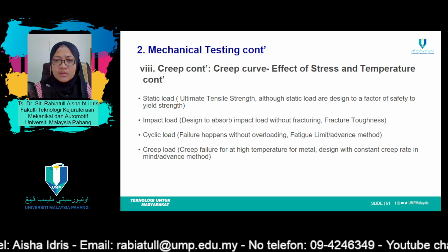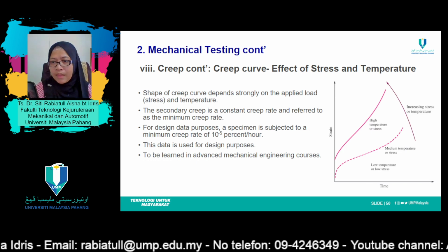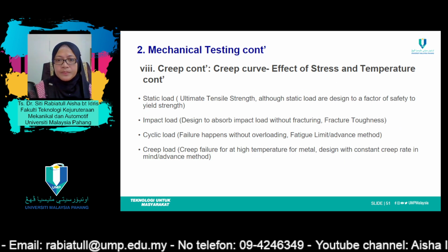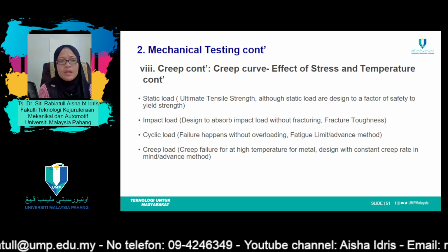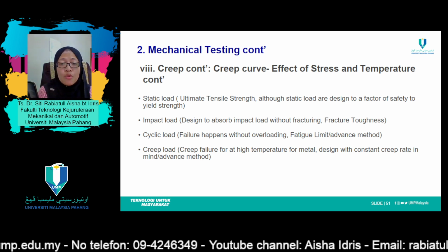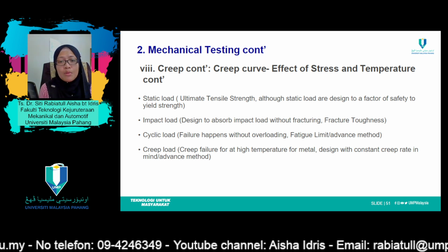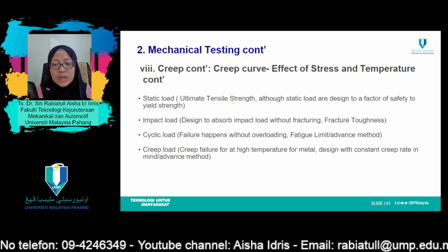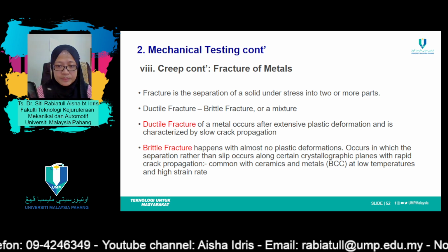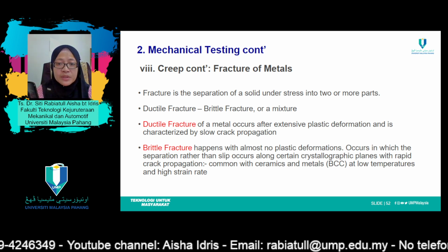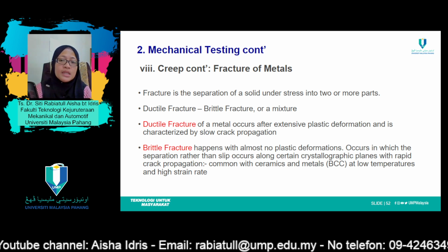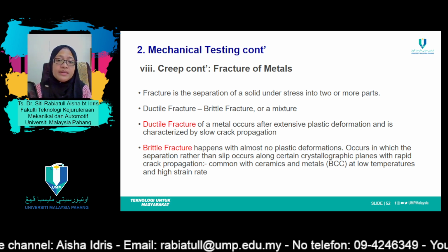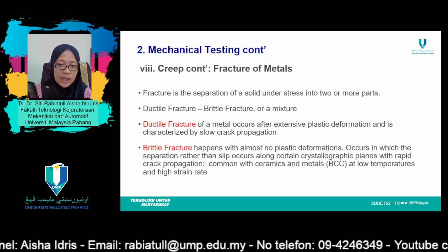Creep curve. Loads that may occur in a creep curve include static load, impact load, cyclic load, and also creep load. As for fracture due to creep, we can find whether it is brittle, ductile, or a mixture of ductile and brittle.